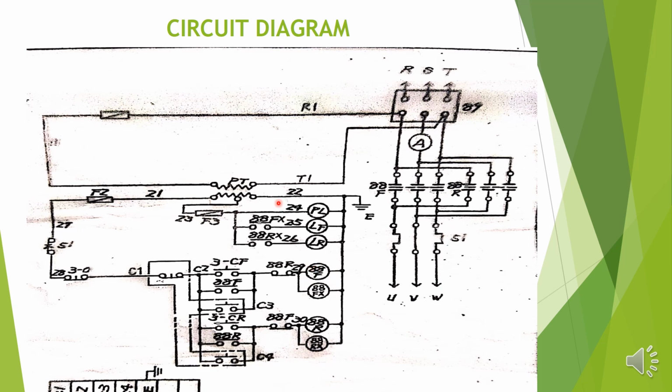Okay, so power is coming to the primary winding of the transformer, and power will transfer to the secondary winding of the transformer to 220 volt. Then the common line is connected already here. You see, common is connected to A2 of the contactor coil, and this is the indication lamp that we will discuss later. So power will transfer to here, F2, and power will transfer to F3.